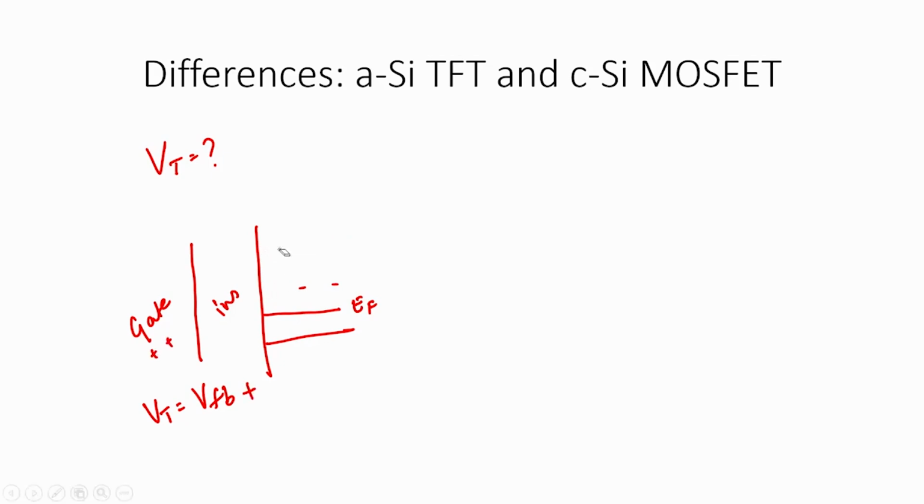the Fermi level moved closer to the conduction band, or in other words there was some band bending, and all the positive charge in the gate was compensated for by the depletion charge in the semiconductor. The next milestone towards achieving threshold voltage was that we needed to deplete the semiconductor enough to get the bands to bend significantly, and finally we had to achieve inversion.